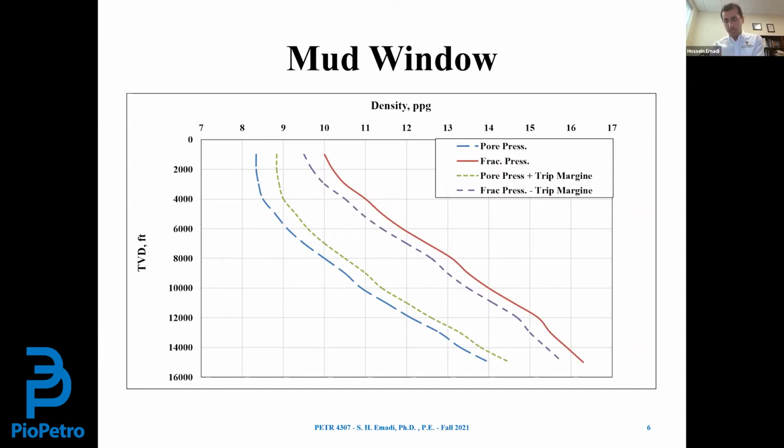So bottom pressure is more than static pressure. When the drill string is still inside the wellbore, bottom pressure is equal to hydrostatic pressure. When we start tripping in, bottom pressure will be hydrostatic pressure plus pressure drop due to friction.